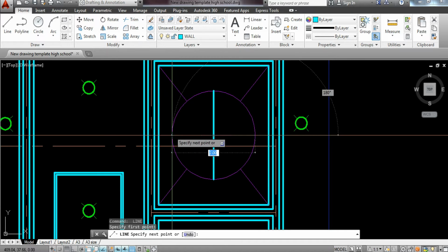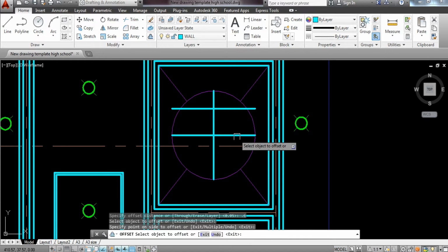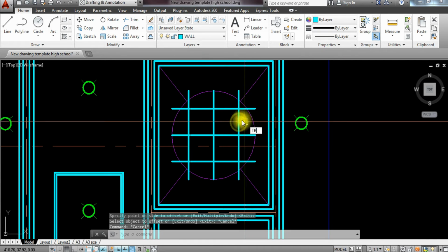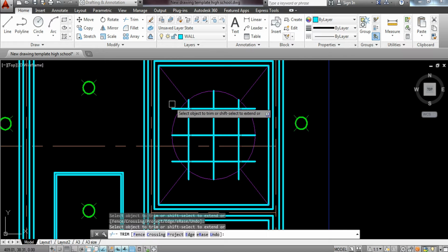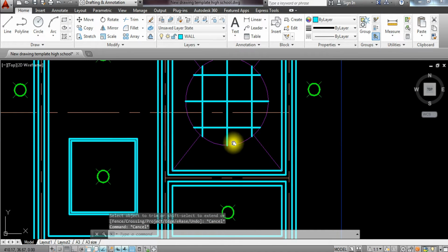For the ceiling joist position, the standard or ideal measurement that we usually use for ceiling joist is 0.6 by 0.6. Here, it looks like the same as the foundation plan, right? But it describes more about the ceiling joist inside the ceiling. These are the woods or metals that you do not see, where your ceiling material will be attached. So, this is what we call the ceiling joist.